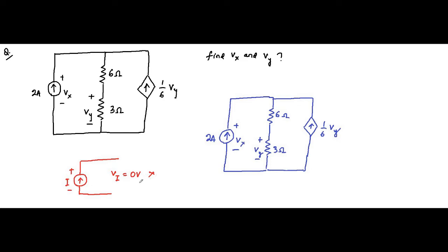So it is wrong. There is some finite voltage across this current source. Why do we make this mistake? Because we never ask such types of questions. It is very rare you will find. Similarly, the current supplied or absorbed by a voltage source, depending on the circuit arrangement, if it is flowing in the opposite direction, then it is absorbed. These two things are very important.